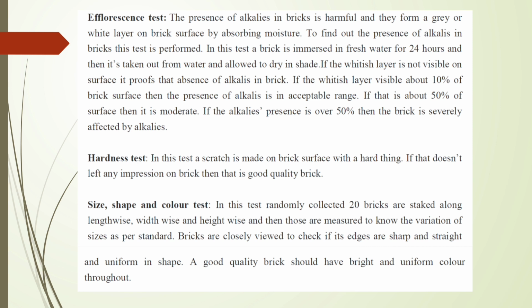Hardness test. In this test, a scratch is made on brick surface with a hard thing. If that does not leave any impression on brick, then that is good quality brick. Size, shape and color test.